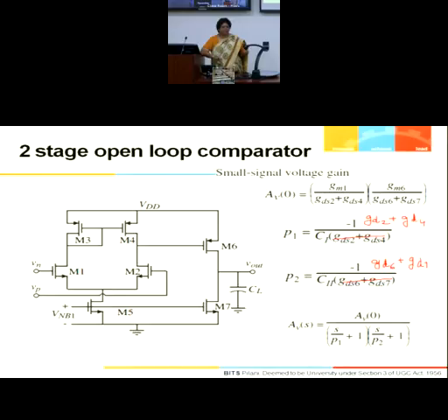But then look at the expressions. The pole expressions are nearly the same, and the R values will also be nearly the same. I assume that the poles will be close together. Both the poles will be dominant. Since the poles are close together, I will get this kind of transfer function. I am not getting a 0 here, because this transfer function does not contain a transmission 0.